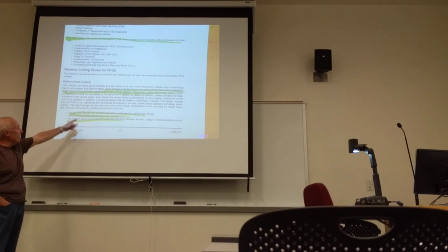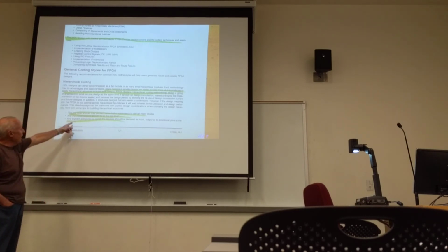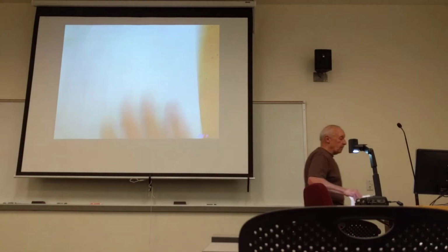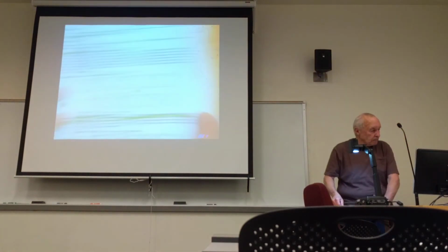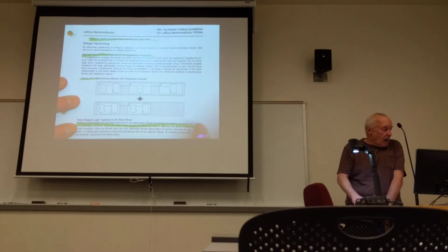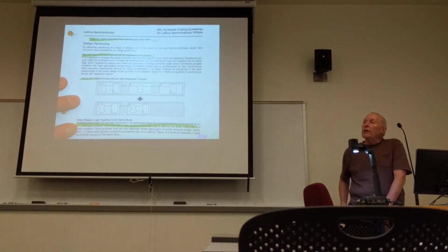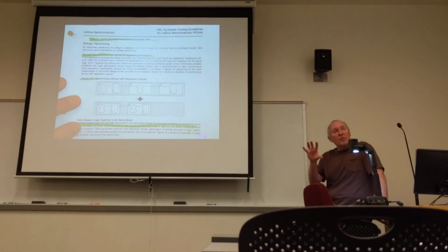Any I/O instantiation should be at the top level of your hierarchy, and any signals going into or out of devices should be declared as input, output, or bidirectional ports at the top level. And memory blocks should be kept separate from other code. So if you're going to infer a memory, that should be in a completely separate module, not buried in some other module.